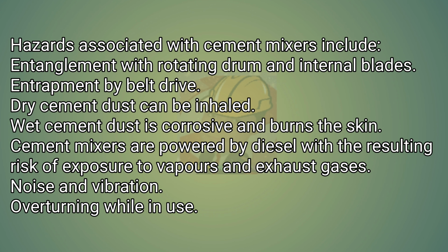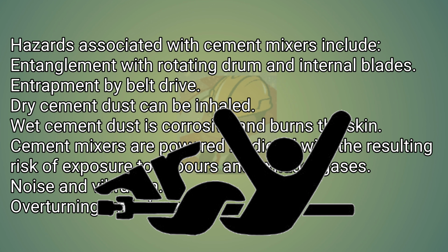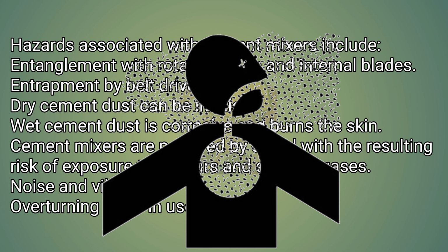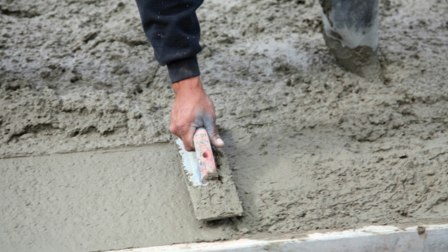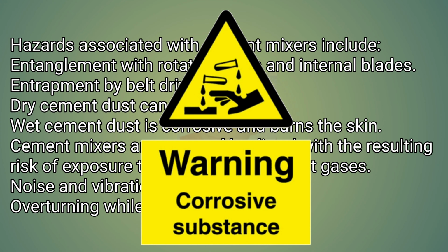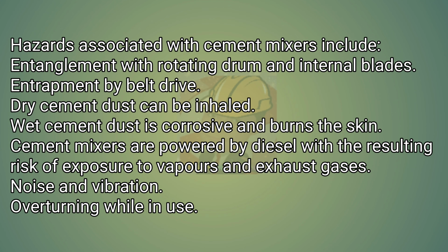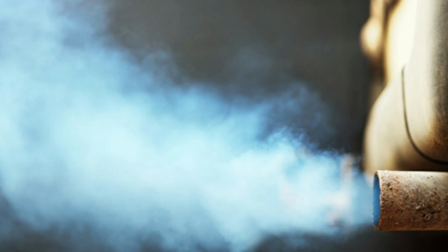Hazards associated with cement mixers include entanglement with rotating drum and internal blades, entrapment by belt drive. Dry cement dust can be inhaled. Wet cement dust is corrosive and burns the skin. Cement mixers are powered by diesel with the resulting risk of exposure to vapors and exhaust gases. Noise and vibration. Overturning while in use.